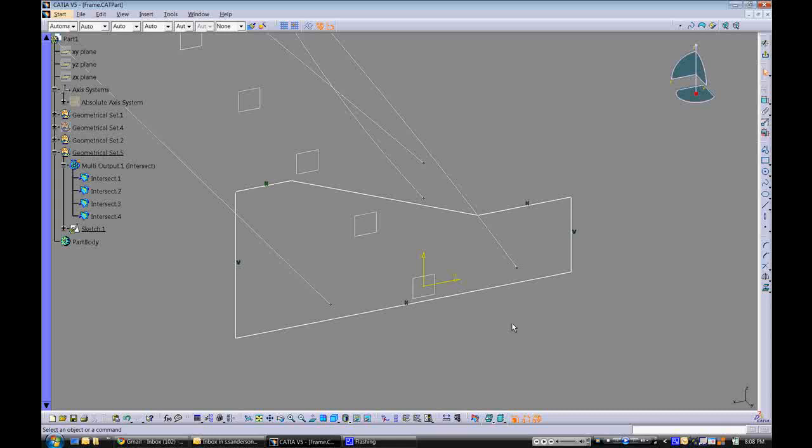So in this case, we're going to go ahead and create constraints between 4 of our corners, our vertices, and our 4 reference points that were created with the intersection tool. So we'll go ahead and use the control button to multi-select. So we selected the vertices, and you can see if you're having trouble picking something, if you hit the Alt tool and click, it brings up this interface which allows you to specify more specifically which element you're trying to select, which is pretty useful.